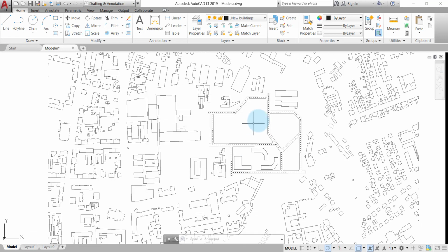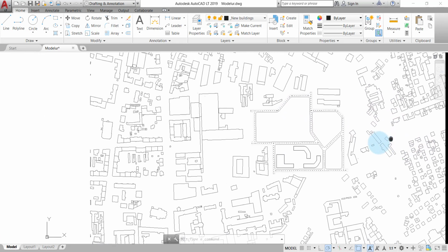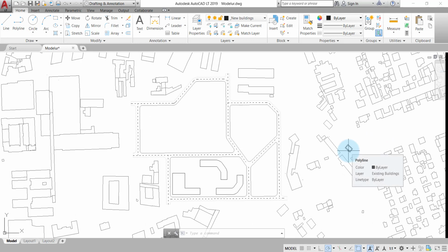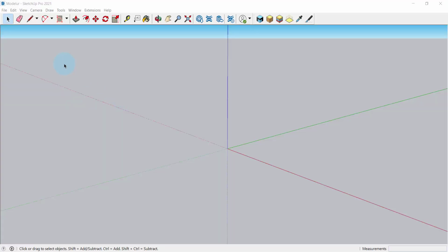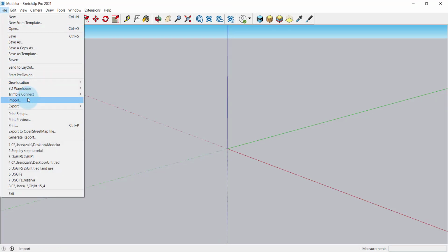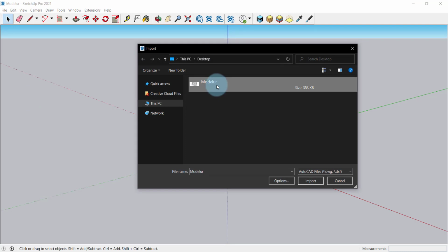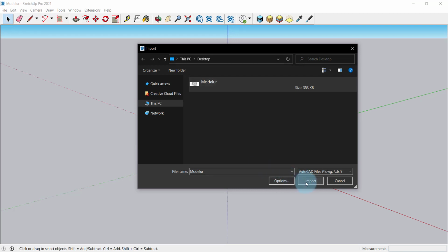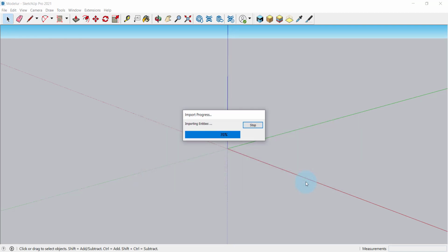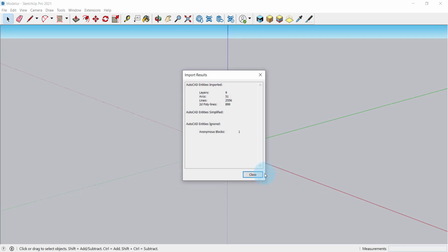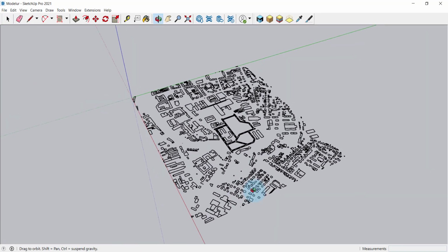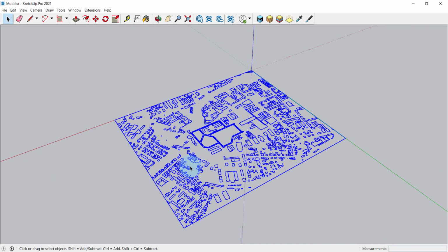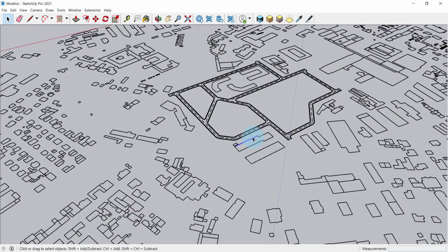So, let's say you have a basic 2D plan of your site, city blocks of parcels, some roads, urban morphology of existing urban tissue, etc., and you want to create a 3D model. In SketchUp, I'll go to File, Import, and import the file with my AutoCAD line work. Select preferred options in Options and click Import. Every time you bring it in, it's one component. So first I'm going to explode it. Right-click and explode. As you can see now, I can click on those individual components.